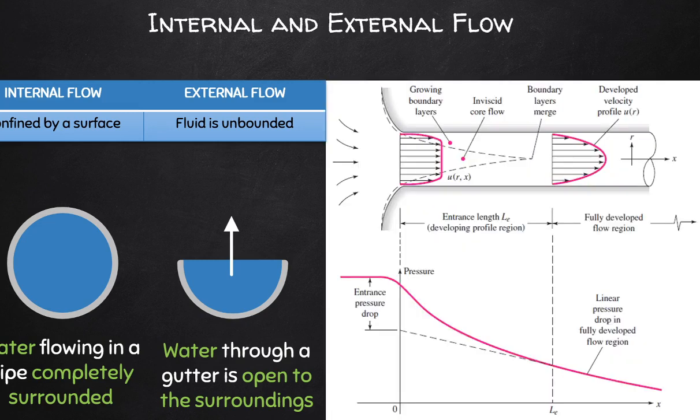These differences will, of course, have an impact on phenomena such as frictional effects, the friction coefficient, the development of the velocity and temperature profiles, and therefore also how heat is transferred through these two flow cases. For the case of internal flows, we often apply a resistance to the pipe entrances as a Kr factor, and also to pipe exits.